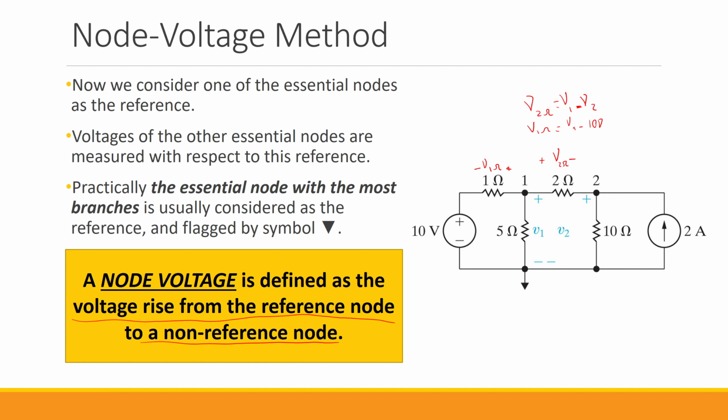Since these calculations are not that hard and practically do not require the solution of any linear system of equations, the node voltage method is preferred in comparison to the systematic approach. Why? Because we reduce the number of simultaneous linear equations that we need to solve.